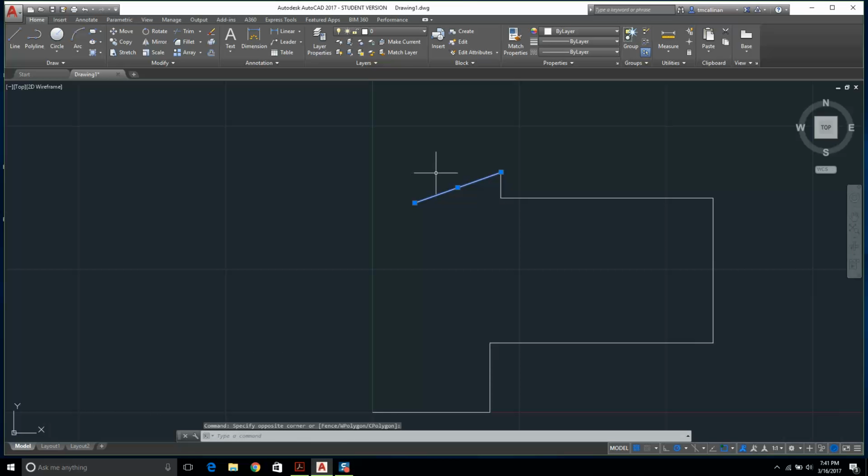I'm going to do it again for you. You're probably confused. All right. I click line. I click this first point. I click @. Now, what does that mean? It means, I think they call that a relative coordinate system. I'm going minus because I'm pointing at the screen here, and you're not seeing that. I'm going in this direction. It's minus 1.470. So we want to go minus 1.470 in the x direction, comma, in the y direction we're going minus 0.535, and we get that. Nice.